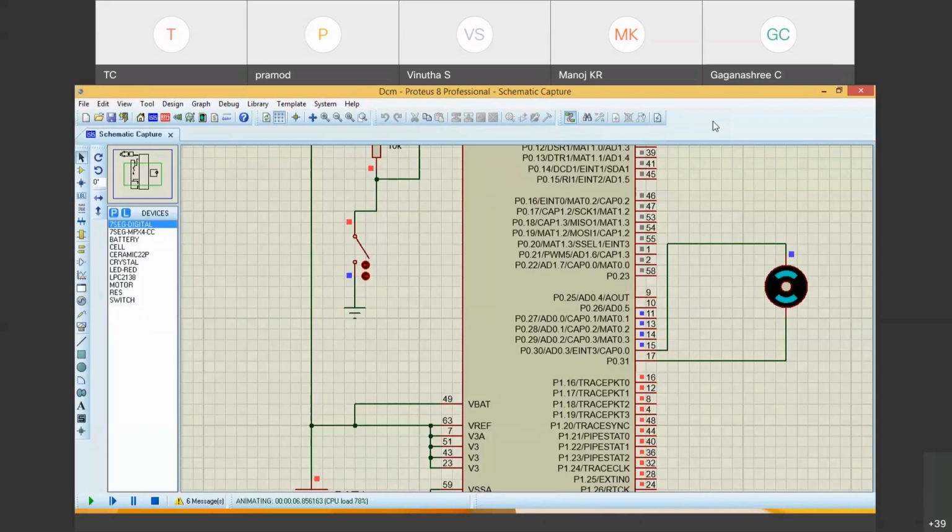So all of you practice the DC motor today on your own, connecting all the components, realizing the code, writing the code yourself, and becoming more perfect at writing the code and executing it perfectly. You can build your own code with a different set of instructions also, with IO dir, IO set, IO clear, and IO pin can also be used. Some people will write the logic with IO pin also. That is also possible. So please think in different directions and practice.